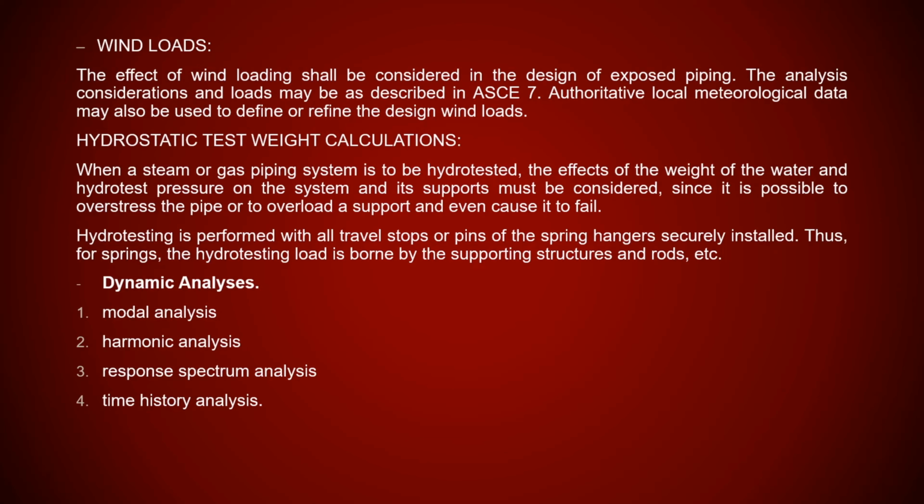What that means is, if you have springs, expansion joints, or any flexible part in the system, you need to lock it. You lock it either by rod or by structure support. Why? Because when you studied the system, you studied it ignoring any flexibility in the system, and the hydrotest in the software does not consider that this part is flexible.